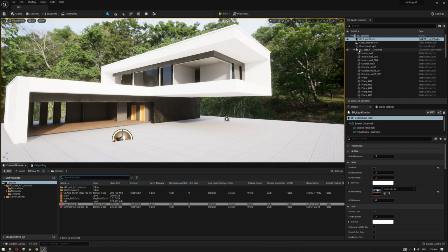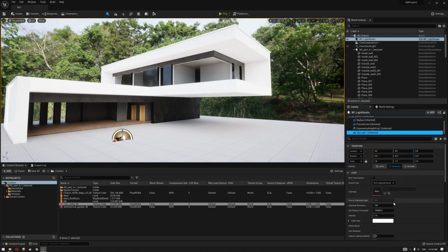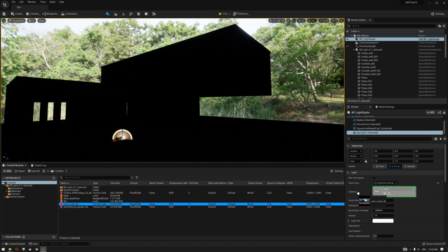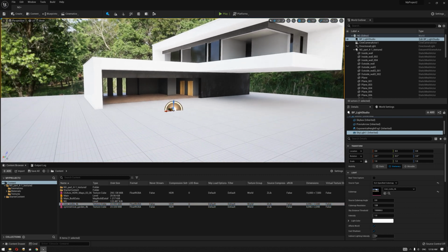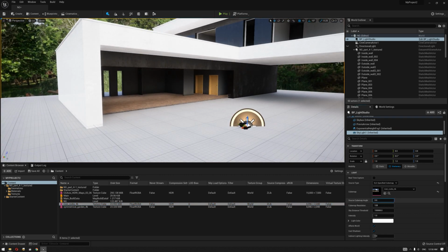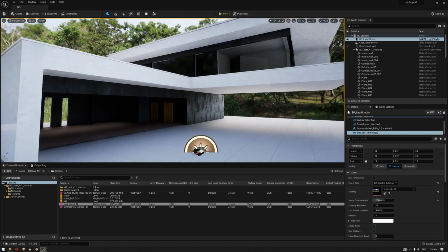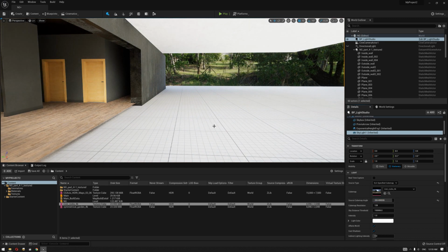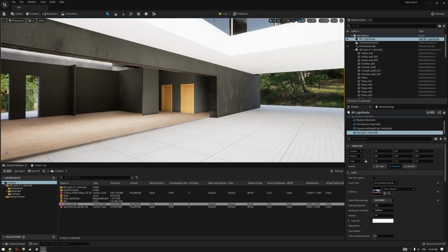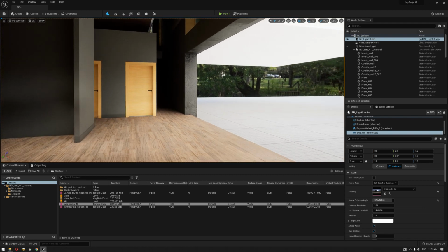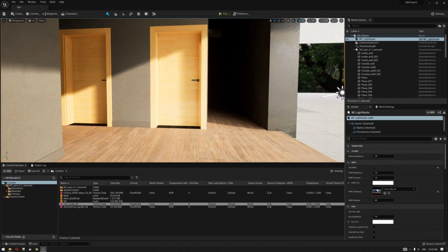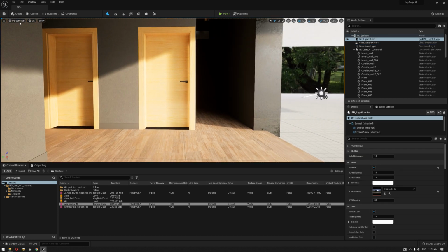Now let's hide the directional light, head to the Blueprint Light Studio, and make sure that we're using Skylight as an HDRI inside the cube map. And if we rotate our HDRI, we'll start to get the light based on the HDRI direction, which is really helpful in terms of ArchViz projects. So it's always useful to let Lumen calculate the settings, and after activating the directional light,